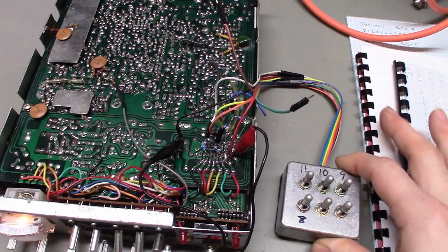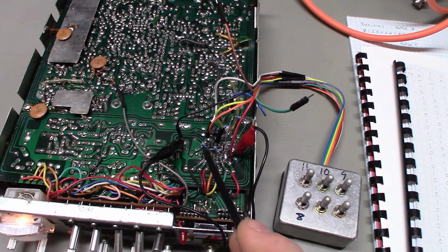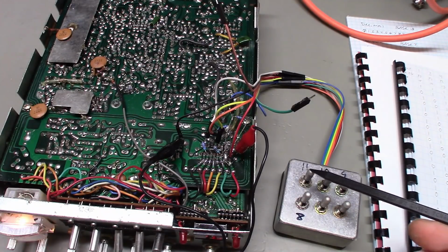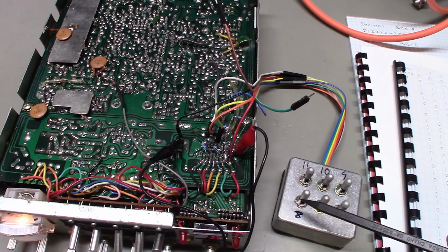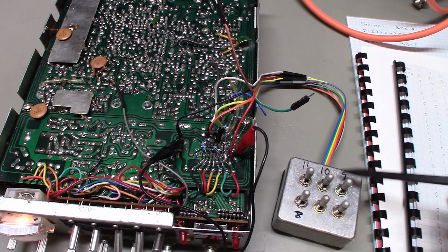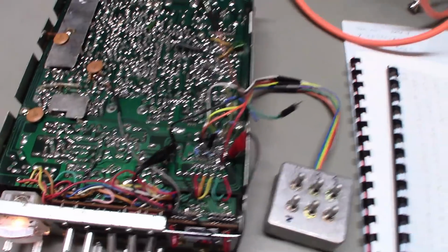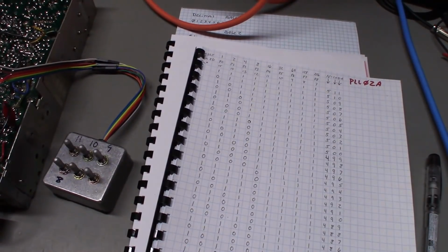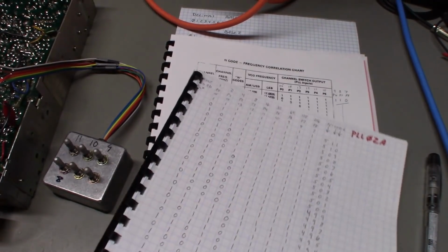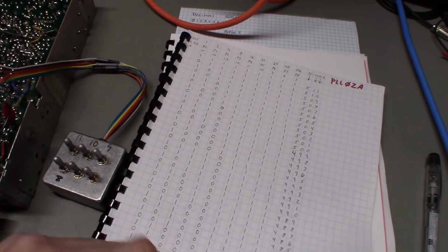So that's what I have here. I've got 4 resistors in here. There's one here, here, here, and here. I have the wires that are attached to the center contacts on each of these 4 toggle switches attached, conversely, to pin 11, 10, 9, and 8. Now, which switch do you need to switch to get extra channels? That's where something like this, your handwritten guide, will come in handy.